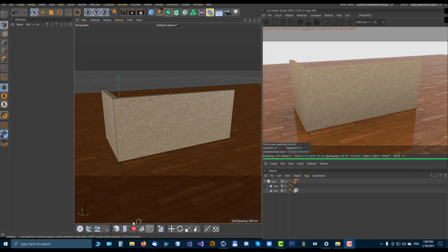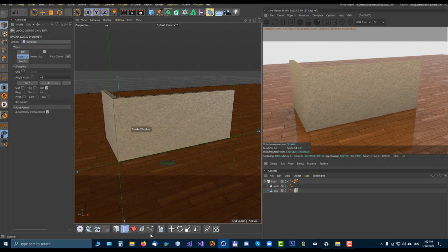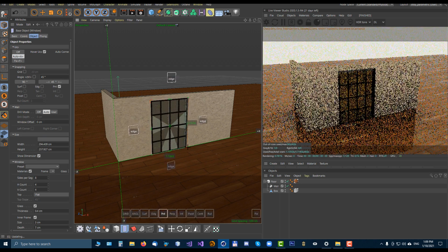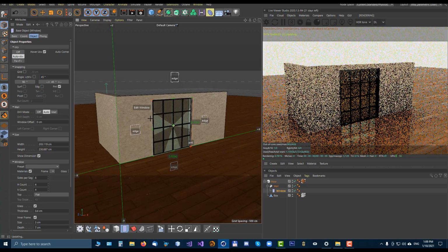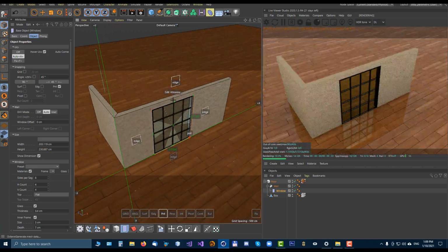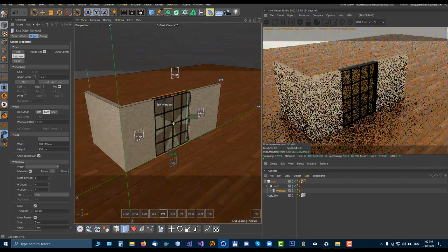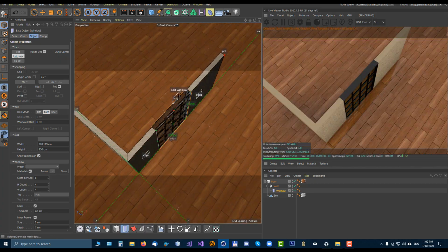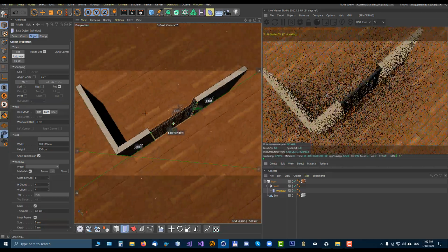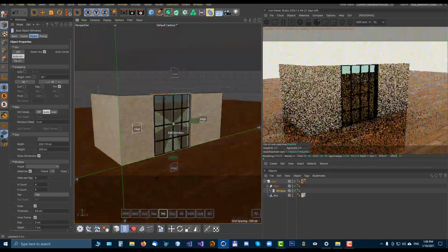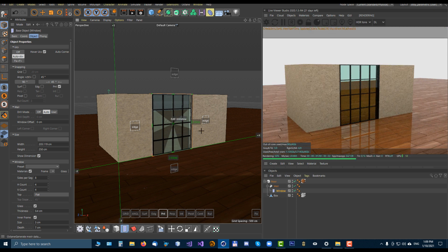Another very nice example of non-destructive Booleans is the window tool or window object. The window object is automatically attached to the wall as a child, and it is automatically doing the subtract operation on the wall. So as you can see, very useful implementation of non-destructive Boolean directly into a parametric architectural object.